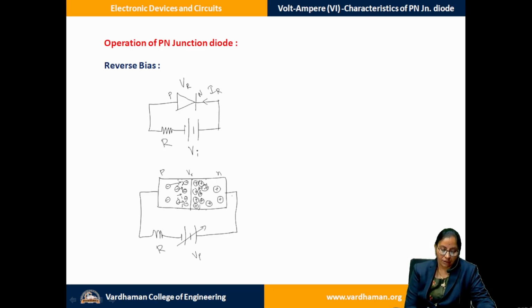And here when we keenly observe how the current is constituted in this particular case, as we know, the depletion layer is also called a barrier, since it doesn't allow the majority carriers. The current because of the majority carriers will be absolutely zero. And let us see the characteristics of the minority carriers in this case. In P material, electrons are the minority, and in N material, holes are the minority. So they cannot cross the junction?